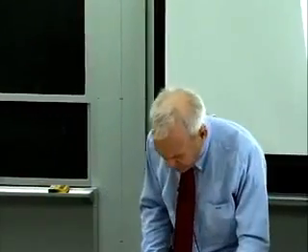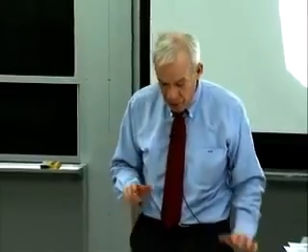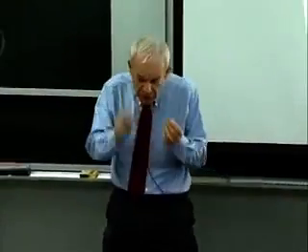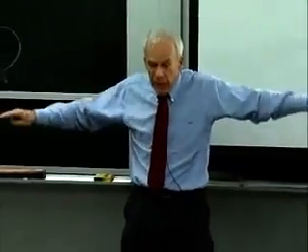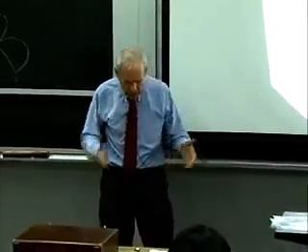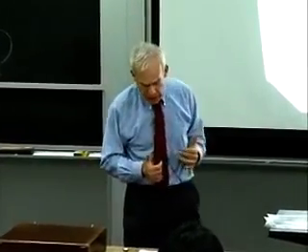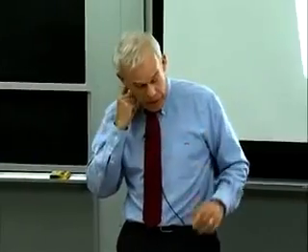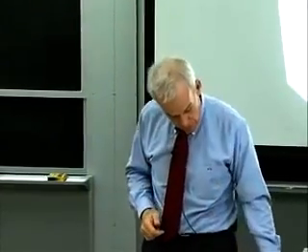So we programmed it up, and we tested it in the simulation because there were a lot of things that weren't in the theory. The effective sampling time wasn't in the theory. The bending mode, possible oscillations, wasn't in the theory. The fuel slosh confusion. So all this stuff had to be modeled in the dynamic simulation that we used to check out the proposed onboard computer programs. And we flew it in that simulation, and sure enough, it flew. The simulation work with all the detailed dynamics in the simulation said, yeah, this will work, this will fly.